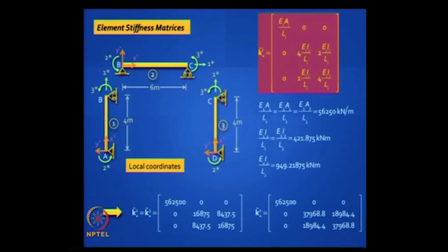You generate the structure stiffness matrix. You do it in 2 phases. First you do this k_i T_Di for the 3 elements. All this can be done by matrix multiplication. If you are doing manually also, it is not difficult, it is only a 3 by 3, 3 by 6. Then you add up all the contributions.